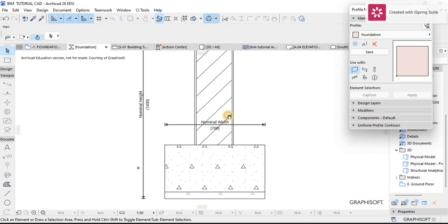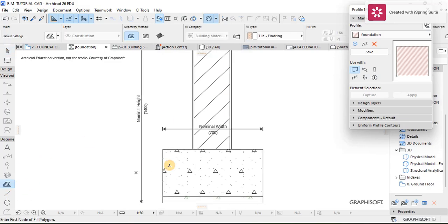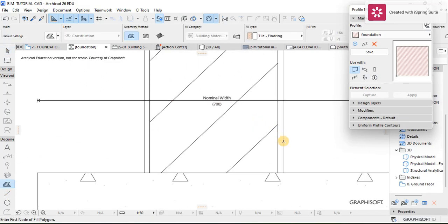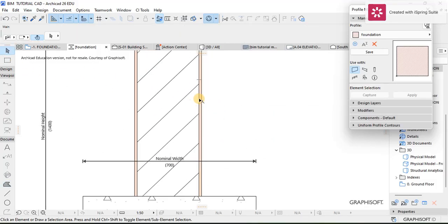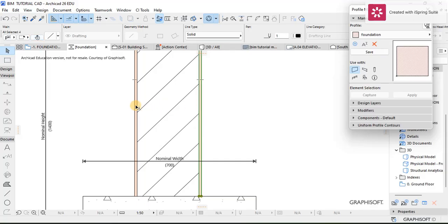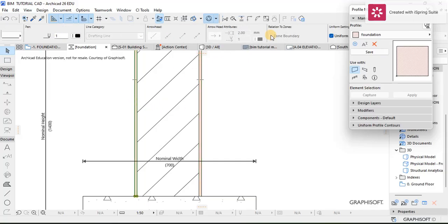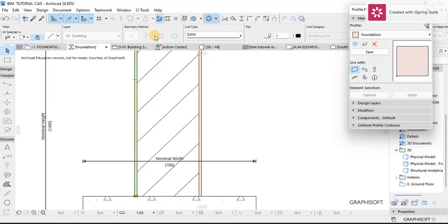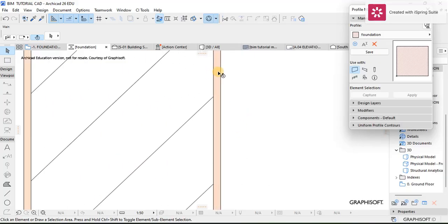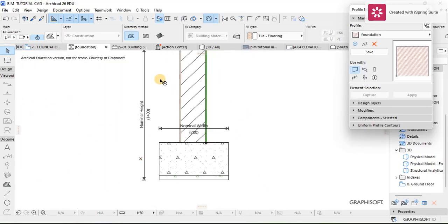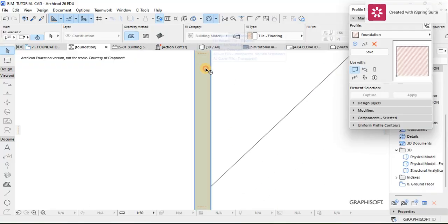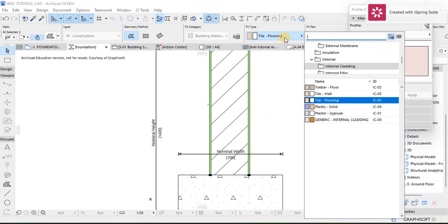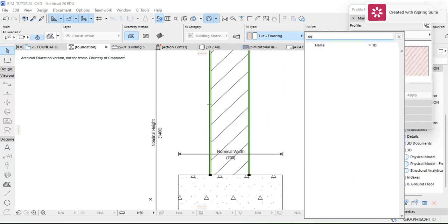We can now fill it too and put the material as a damp proofing. So just fill it. Yeah, with that done, we just select the two fills that were made, then we go and look for, make sure you select the fill, not the line. Then shift and select the next fill. Then we're going to look for what is supposed to be there. So damp proofing.